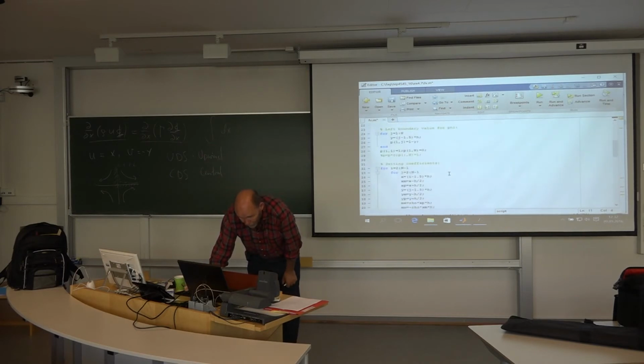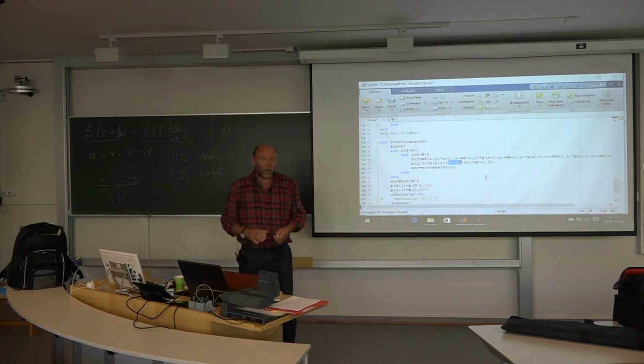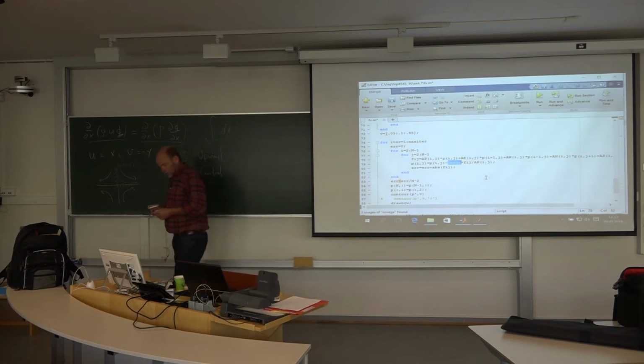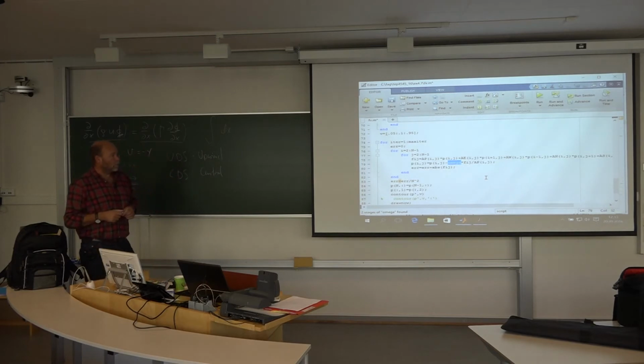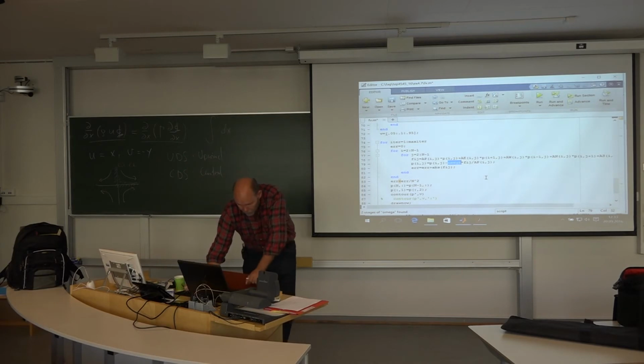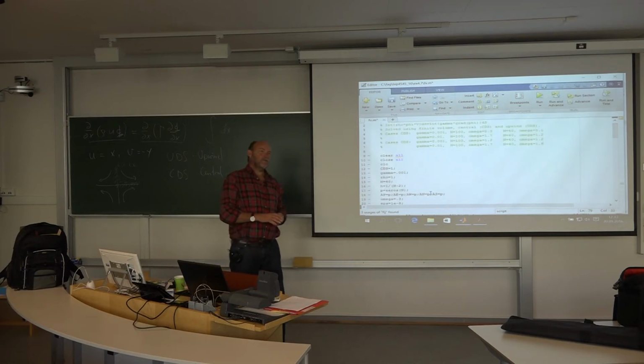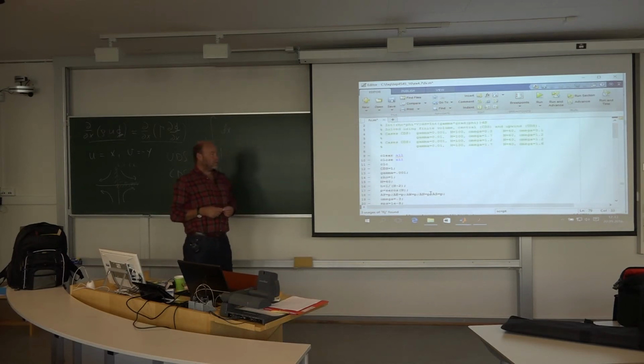And then it's a question of how to solve our algebraic equation system. Here I have set up just the coefficients, and then I use an iterative scheme, the SOR, the successive over-relaxation, the same one as we have in the SOLA algorithm. But here I have to be careful. This omega, if you can recall, a good value was between 1 and 2. And the more unknowns you had, the closer it should be to 2, to be optimum, to be fast, to be efficient.